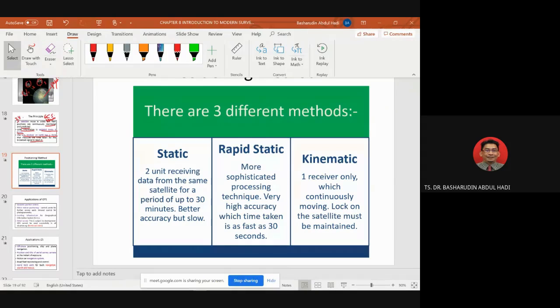You get the position values X, Y, Z, plus the clock time, plus the date. Then you process, clean up the data or do some correction, for the static GPS at point A, and you also have data from the static point at station B. You receive data from at least 3 satellites at each point.